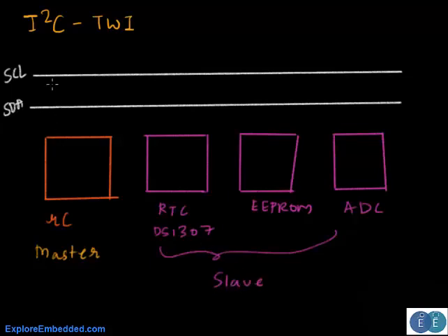And as you could clearly see, there is only one line, and there could be only one device transmitting at a time, while more than one device is receiving. Since the communication needs to be bidirectional, what I mean is the microcontroller needs to speak to a specific device, say an EEPROM or RTC, there is an addressing mechanism for all of the devices. Now before we discuss all of that, say we have the data line which is connected to all of this.